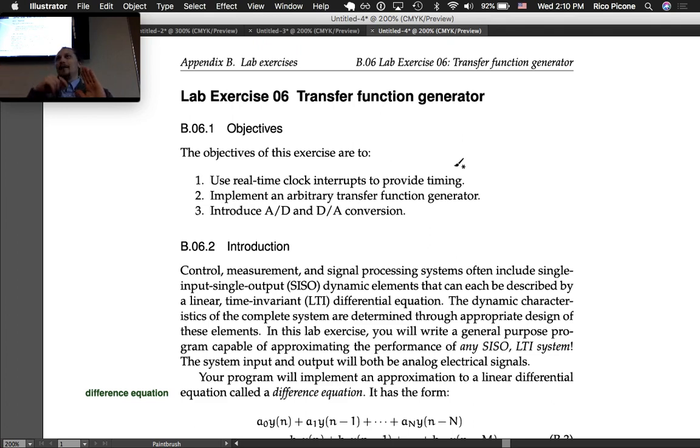You do your stuff in your loop, wait for the next interrupt, and then once you get it, go do the stuff in your loop. As long as the stuff that you do in your interrupt service routine doesn't extend beyond the amount of time you have between interrupts, you're fine.